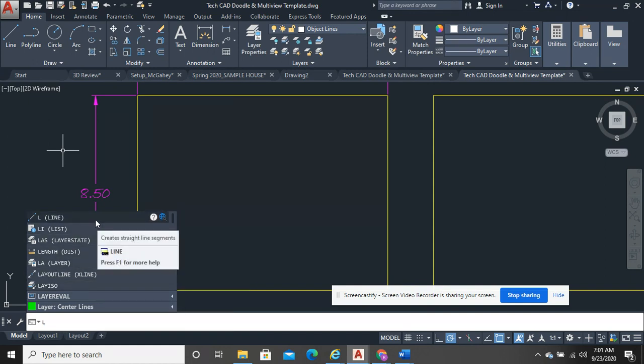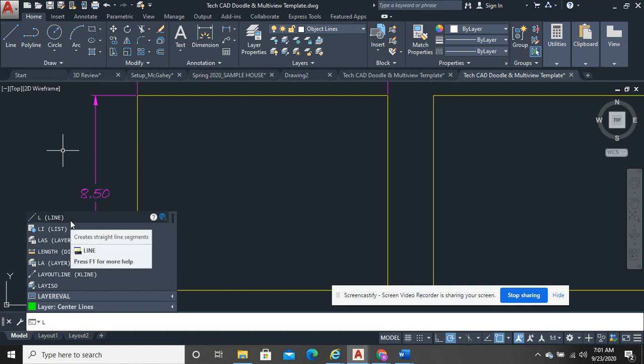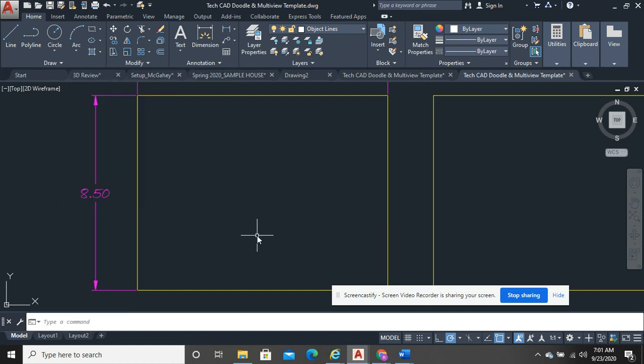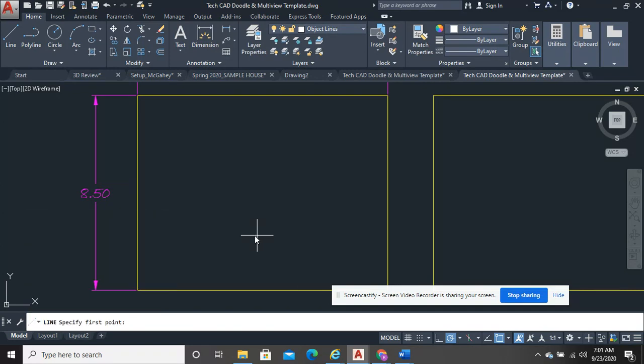So it's every L tool and more. Some that you will never use, but the first one is very popular. You'll use line. A third way you can get to these things is type the letter L, like for line, and just hit the space bar, and that's the hotkey connection. I think hotkeys are the way to go. I can get pretty much everywhere through here without the hotkey, and that works great too.